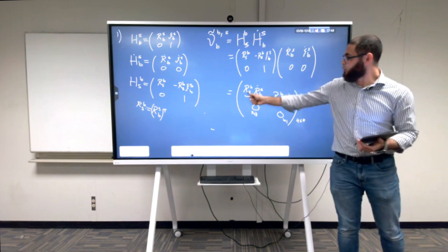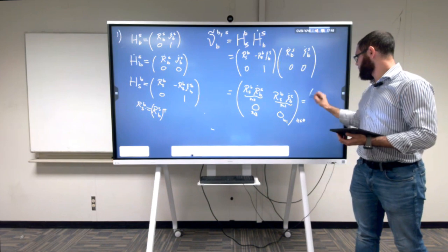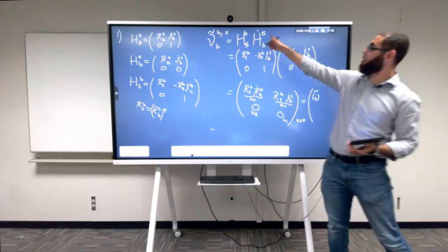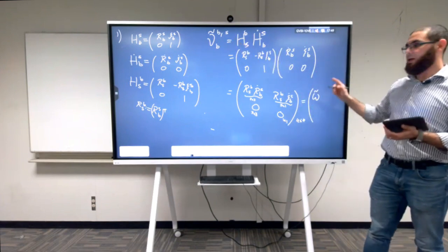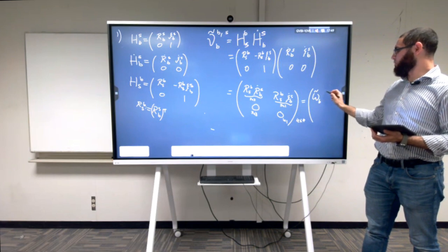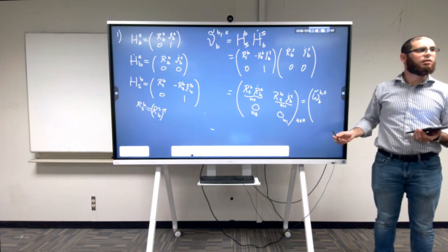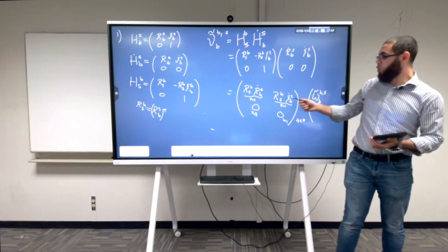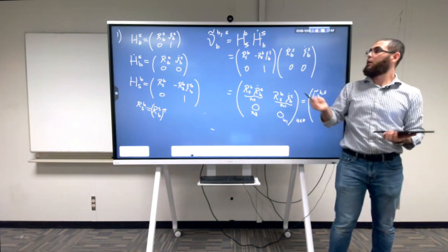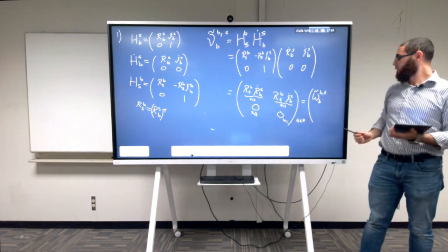Now let's look at this guy. Did we introduce this guy before? What did we call it? Omega tilde. Now can you play the game of the indices and tell me the indices, what they will be? Which one is down? With respect to? Expressed in? And it makes sense, right? So this 3 by 3 component of this 4 by 4 matrix is nothing else than the angular velocity of frame B with respect to frame S expressed in frame B. So there's no magic there. What about this guy?